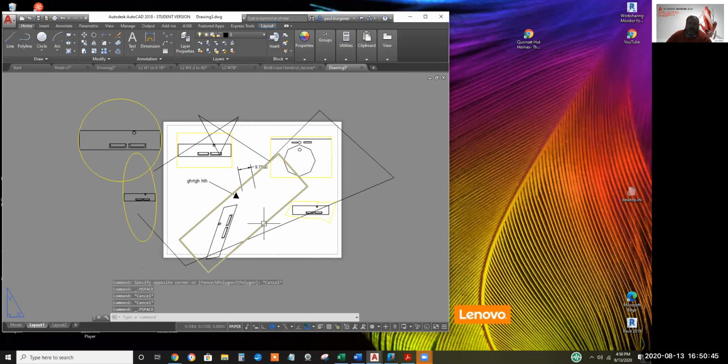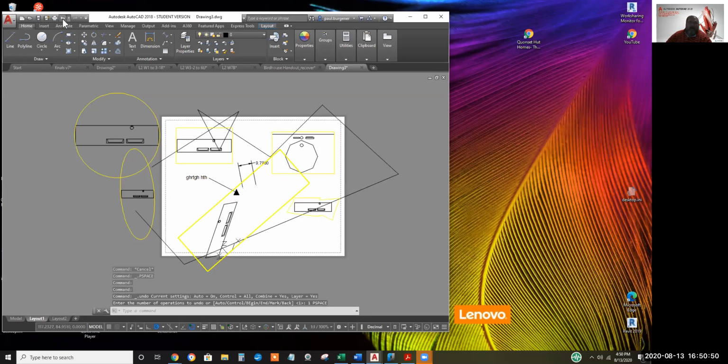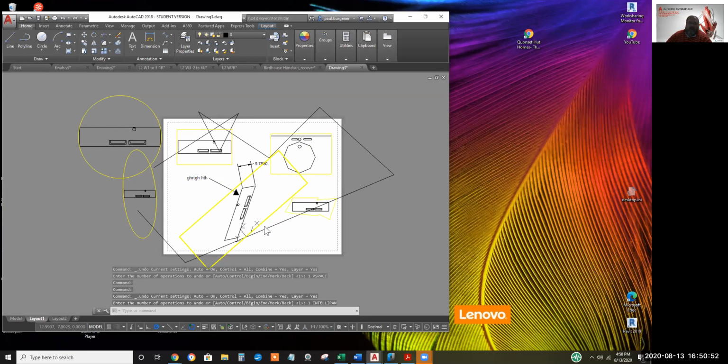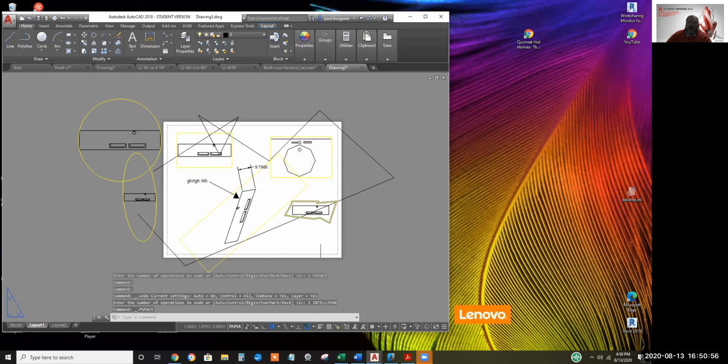So it's a good idea to cut the wires to the remote control cameras before you start putting annotation in paper space that points to the stuff seen through the viewports that live in model space.